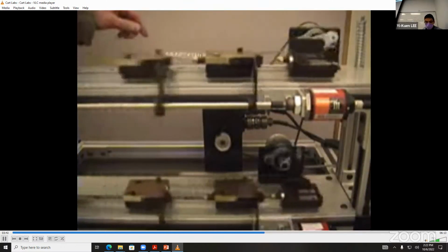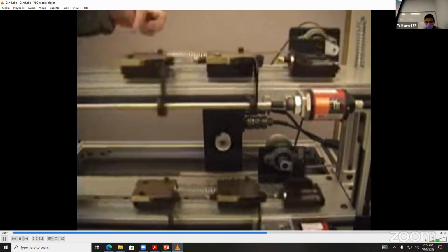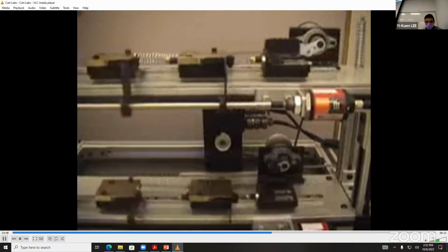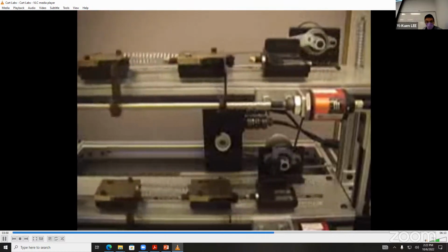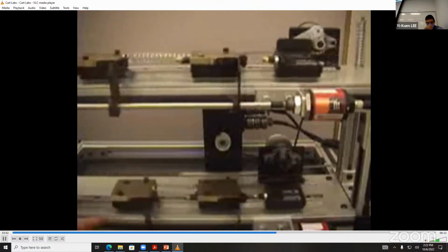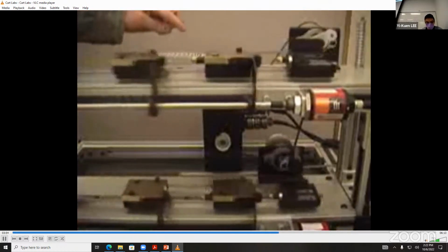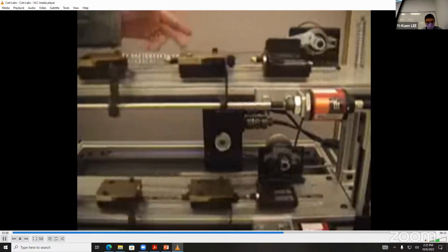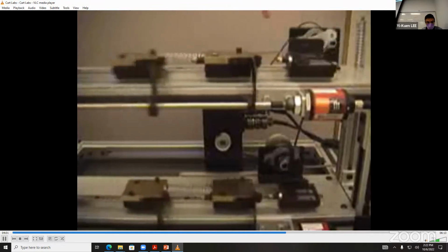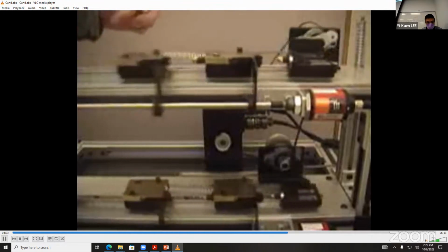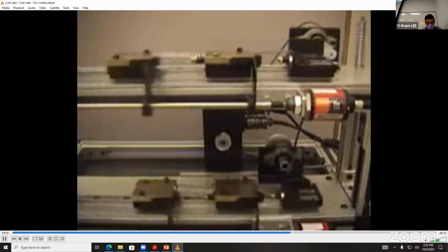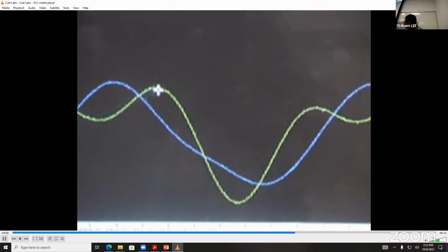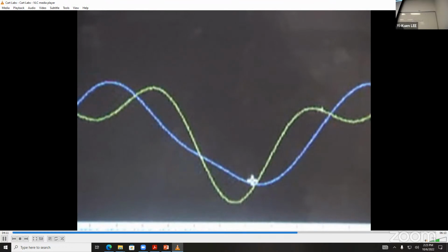Okay, so here our driving frequency is half the natural frequency of the system. You can see the slider crank is creating resonance in our output mass, whereas the Scotch yoke is not. It's because the second frequency component of the slider crank happens to be twice the natural frequency. So because we're driving it at half the natural frequency, we're exciting this natural frequency vibration, this resonance. Here we can see the output response of the slider crank in yellow and the Scotch yoke in blue.